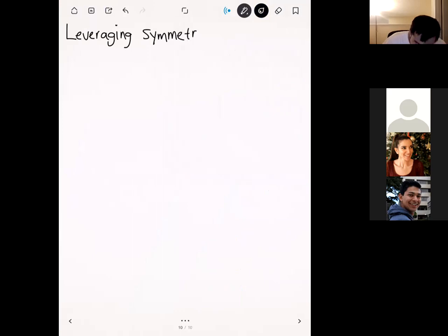And that's a big deal. Okay? And so I had several of you reach out to me from the previous activity about the mesh with the 2.5 millimeters, right? A lot of you ran into that error where ANSYS tells you that you've exceeded the problem limits for your license. Okay. What that basically means is that you have too many elements in your mesh.